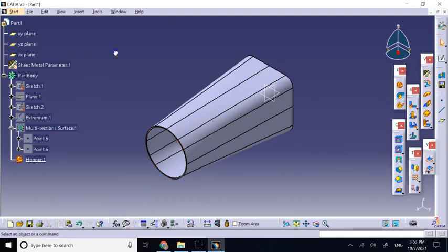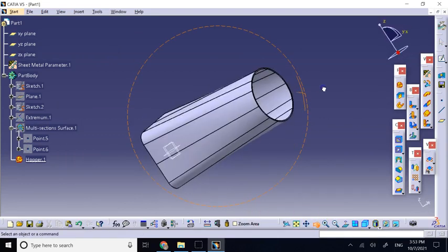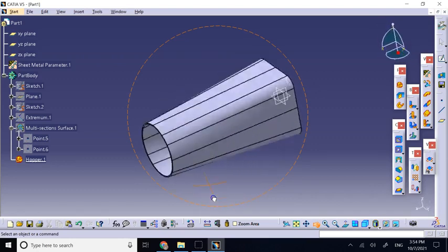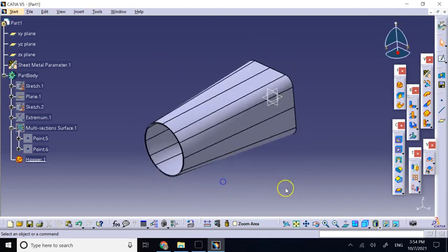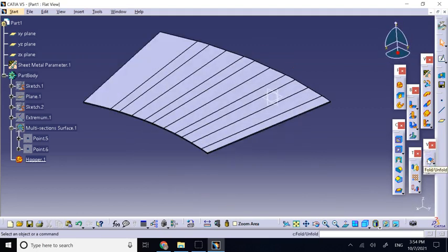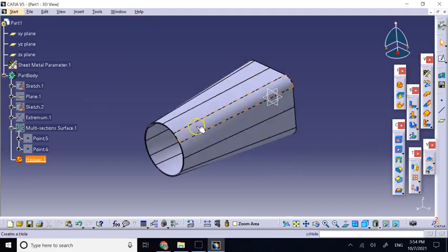And now you can hide this guy, and there we go. You see, you got yourself a sheet metal that is a little bit complicated. And what do you need to cut on a flat sheet of metal to make this happen? You can use the unfold and see, hey, this is exactly what I need to cut. You can make all the measurements. You can make a drafting out of it and give it to the technician to cut it and then fold it back together, and maybe at one edge they need to do either a permanent connection or a hem or something and put it together.